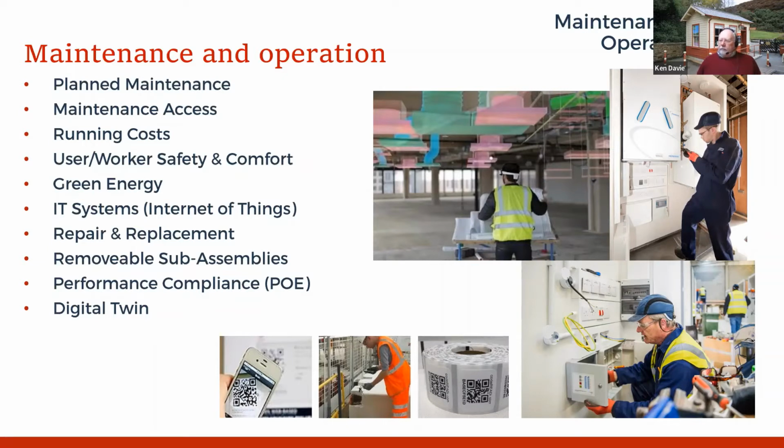Although they have improved over the years, if you go back a few years, concrete structures were probably plus or minus 25 mil, whereas the tolerances are far better now. But certainly when you're actually manufacturing something, you're working to tighter tolerances, and the tighter tolerances result in a more energy efficient structure.